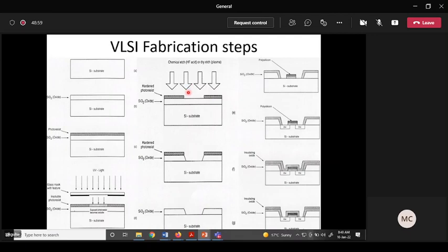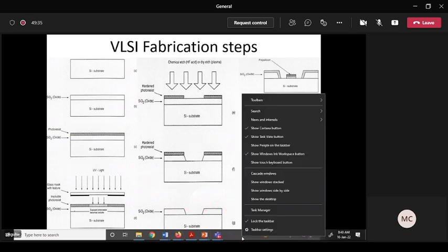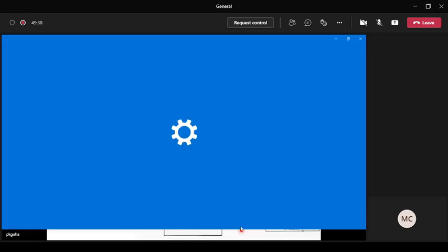You can remove the resist using a developer, and you can then open a window. You can then remove this oxide layer by an etchant, for example buffered HF, hydrofluoric acid, or some chemical agent to remove SiO2, and then you have a window like this. You also remove your photoresist, and you have a window like this.